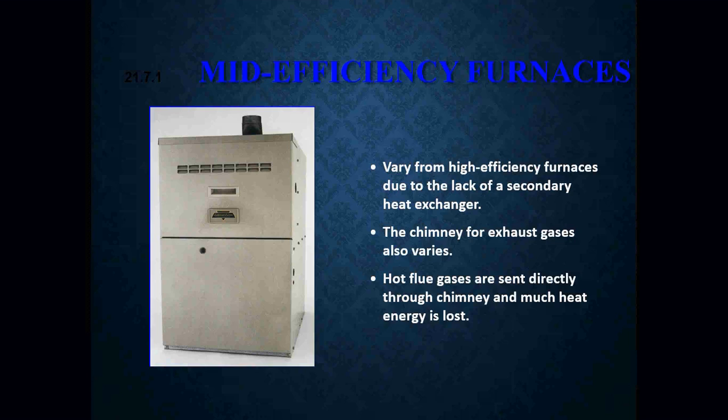Mid-efficiency furnaces will vary from high-efficiency furnaces due to the lack of that secondary heat exchanger. The chimney with exhaust gases also varies. Hot flue gases are sent directly through the chimney, and much of the heat energy is lost.